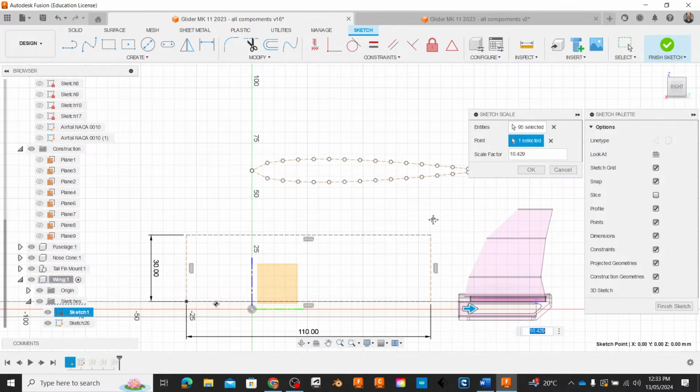Okay, so we need to firstly just get our scale in proportion. So this is about 1 millimeter here. So what I'm going to do here is put a little round at the back. That can be an arc or a circle. There's a number of ways you could do it. So an easy way is to just cut it like this. Then trim out the parts that you don't want.